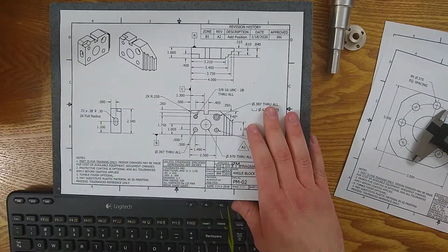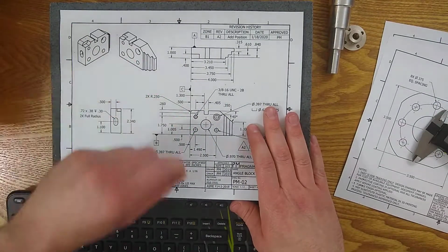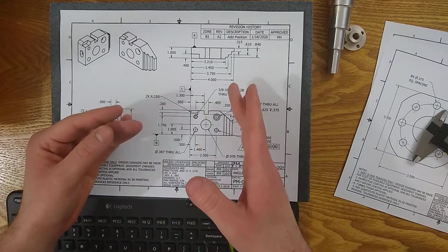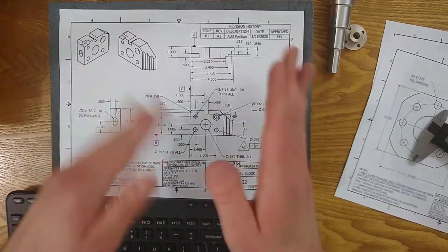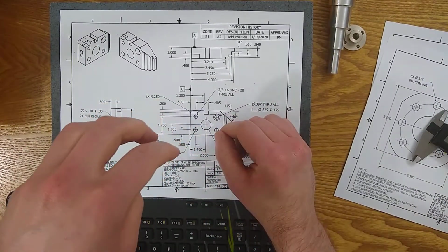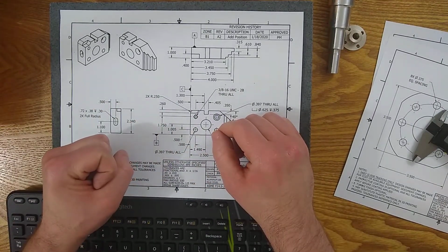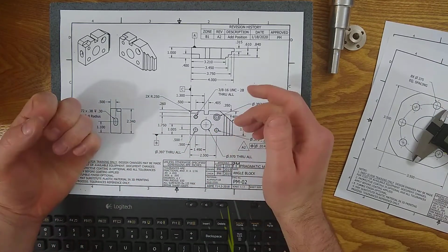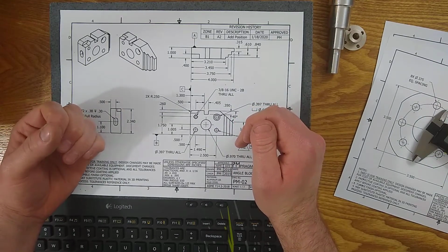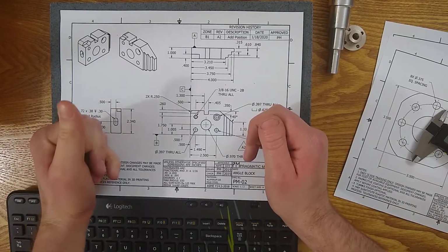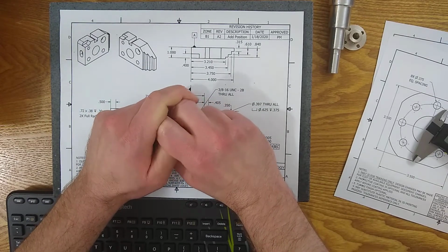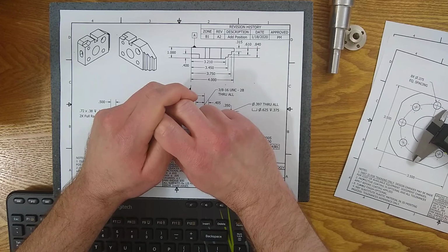If you're going to get red lines, as I talked about in one of the other videos, make sure they're signed and dated and very clear about the markup there. When it's redlined, it becomes official. Anything less than a red line is not official. And in most cases, it has to be an engineer. I've been in cases where a production manager does it and has the authority, although that's not always kosher with every manufacturing process. But whatever your company policy is, just follow it for red lines.